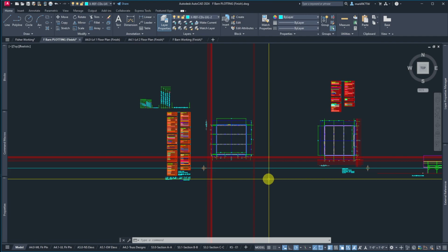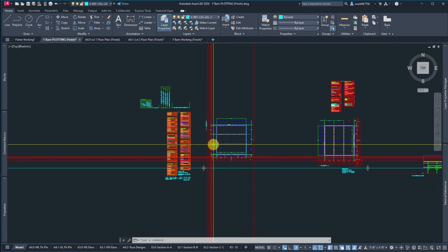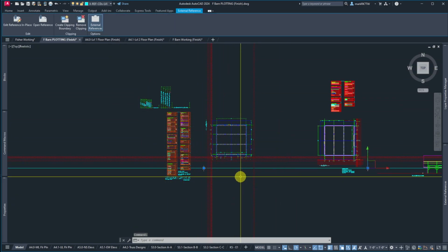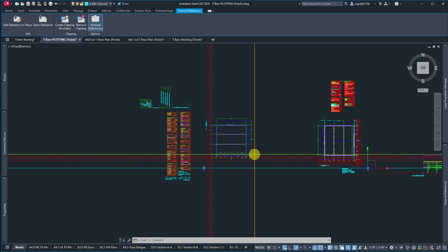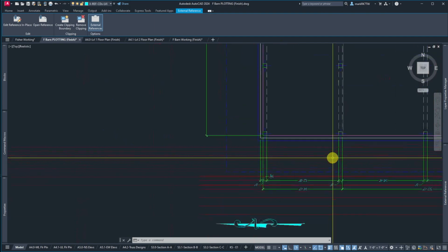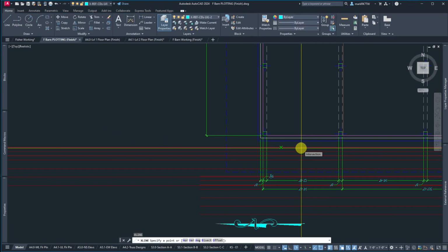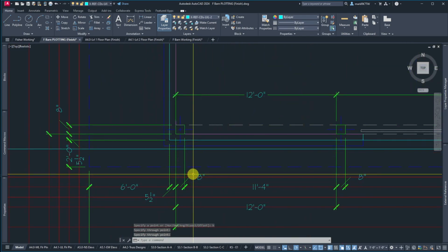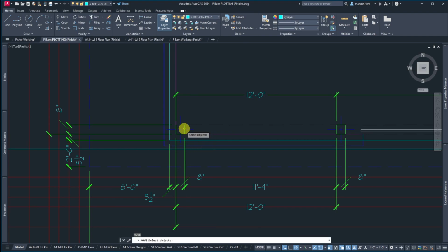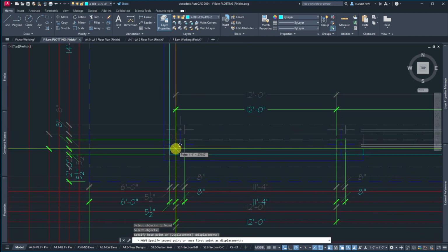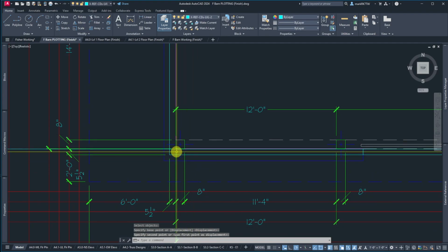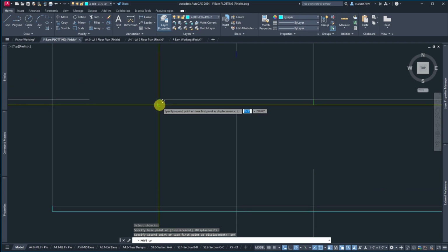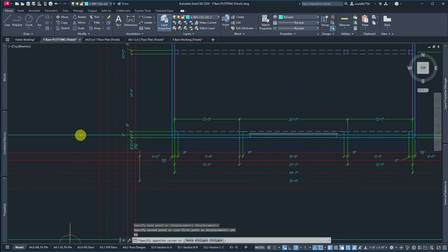So now I can make it closer, but before I make it closer, let's X-clip it. X-clip's going to get rid of all this extraneous garbage because there's my XREF, and I don't need all that stuff. It appears the walls are what's important. So let's go XL, H, let's drop that there, and that should be right through it, and it's not. So I'm going to move this from here down to there. It probably came in incorrect and I missed. Move that from there to perpendicular to there. And now we can get rid of this guy.